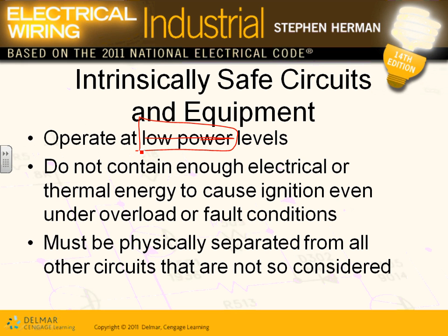So low power. Okay, so what do we mean? They don't have enough energy, guys, electrical or thermal energy, to ignite the surroundings, and Chris, that's all I care about, even under overload condition or fault condition. This is one of the most important things. You guys are going to be journeymen or masters; this is what they test you on. Can an intrinsically safe system under fault condition or overload condition ignite the surroundings? No. Under normal condition, of course, no.